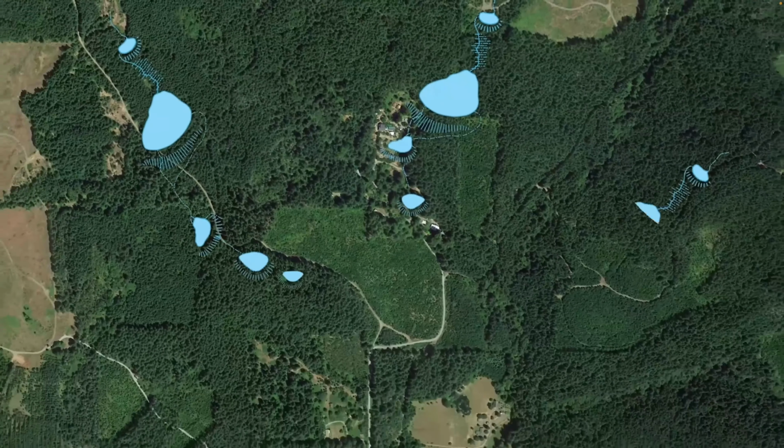So if you have clay, the bottom of the excavation, and this is called the cutoff excavation, should be at that impermeable layer and connect with the dam. The dam then sits on top of a keyed in depression that goes even deeper into that impermeable layer.